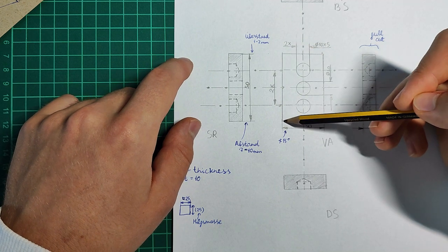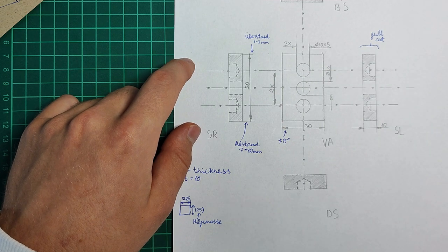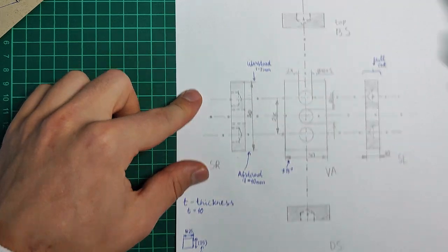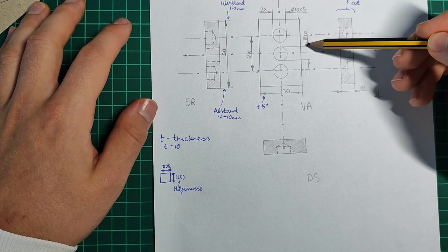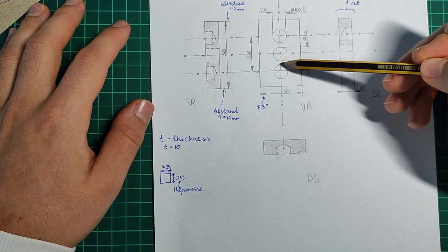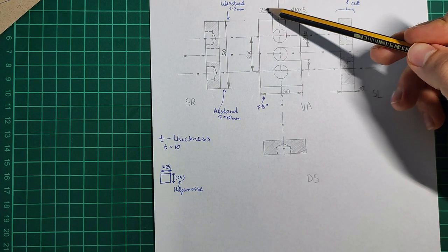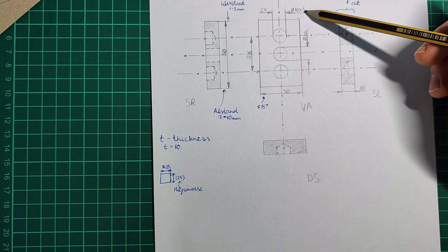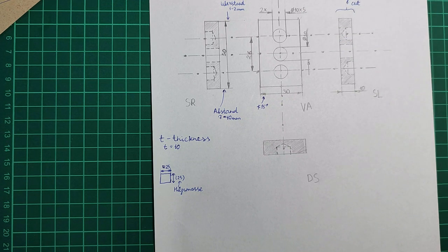Okay, when we have constructed all necessary lines, the holes, we need to put arrows in the correct way. Here is only one of the possible solutions. We can show the diameter of this central hole, and for the upper and lower we can just write 2x and the same diameter and times 5 in depth.